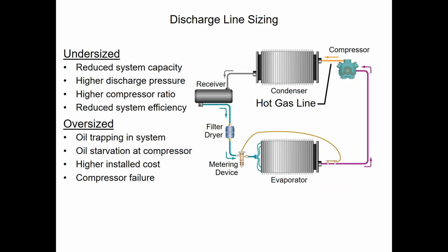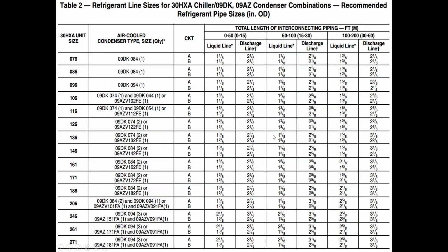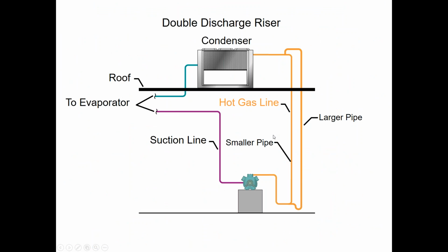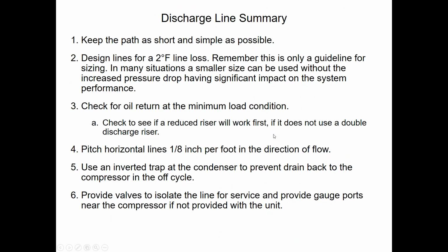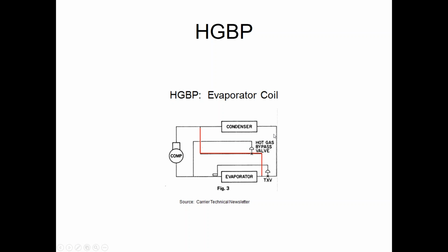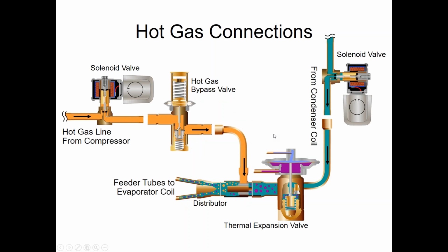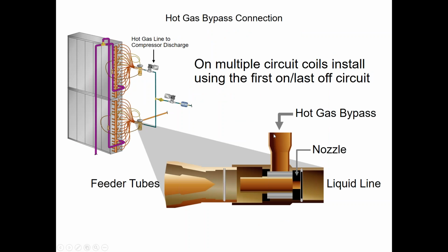So no, when I say oil, I am talking about compressor oil. Yeah, I've found over the years a lot of people realize there's oil in the compressor. There's mechanical parts grinding together, but they don't realize that the oil is entrained with the refrigerant. They don't necessarily get that until they have a problem job the first time. And then they're like, oh yeah. Right. Installers realize it, but on the design side, we don't always realize.